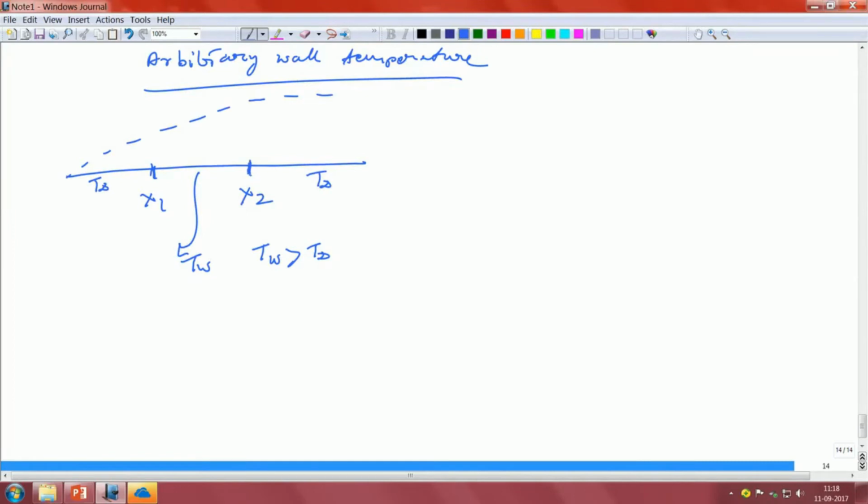So it is a plate in which only one segment of the plate is actually at a higher temperature than the incoming flow field. The other parts of the plate are at whatever temperature, in this case the same as the ambient. If the temperature was the same as the approaching temperature, you know quite well that no velocity profile will be developed, right? There will be no profile developed if the temperature is the same.